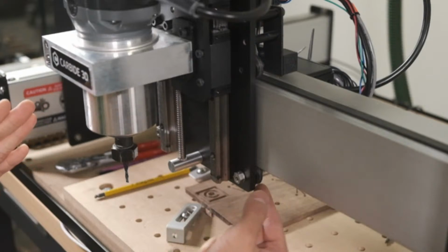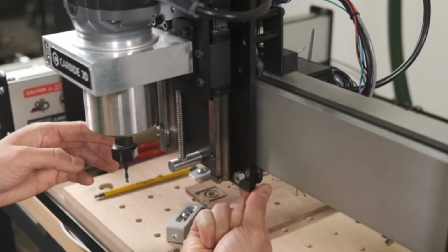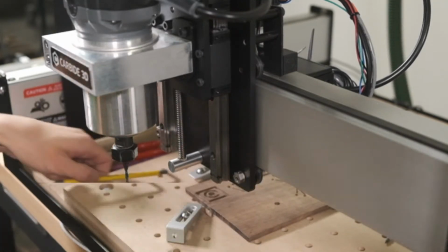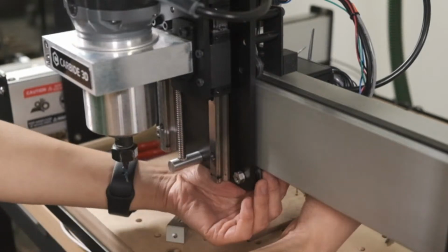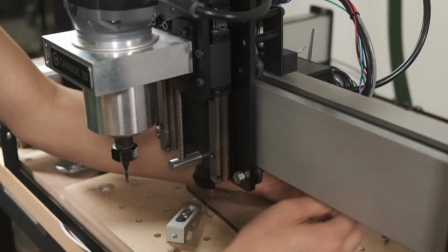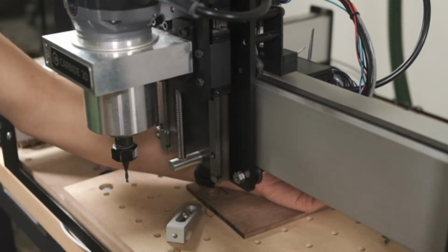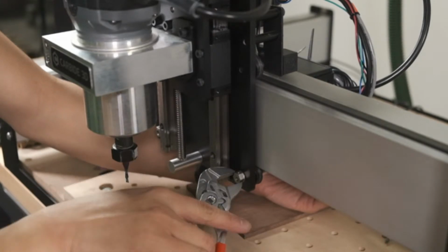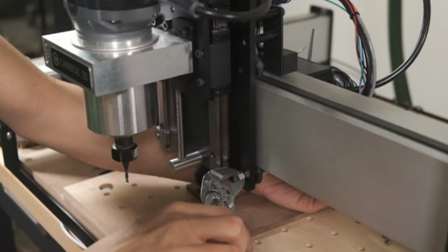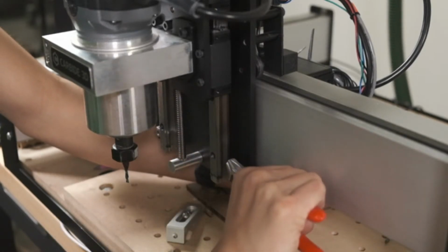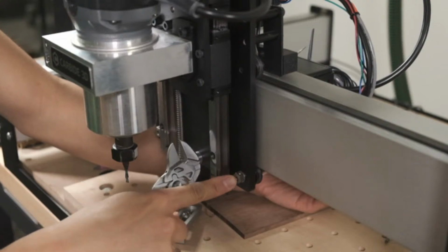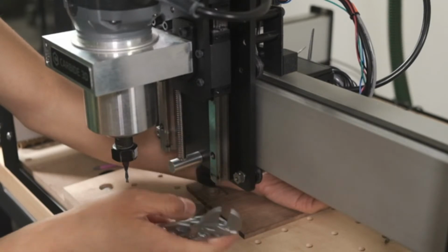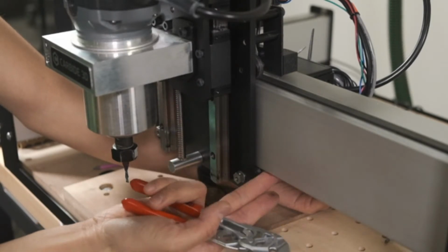and forth, I can barely stop the wheel from spinning if I really pinch the wheel. Don't get your fingers caught under it as it rolls. Use a wrench to prevent the bolt from loosening. Your favorite pair of wrenches, I think this is a 10 mil if you have an actual proper spanner, and then rotate clockwise. So this eccentric nut, you want to bring this around so that it moves the axis of rotation of the wheel up and brings the wheel closer to the rail.